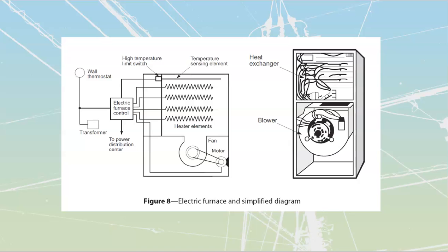What they are is basically an accumulation of baseboard heating elements. That's what all of these are over here. We're going to have a whole pile of these inside of there, and then a fan that is going to take air from the rest of my house, heat that air up and push it out to other areas. Instead of turning on all the elements at once, we are able to turn on just a couple of elements based upon what the incoming temperature is and what the outgoing temperature is going to be.